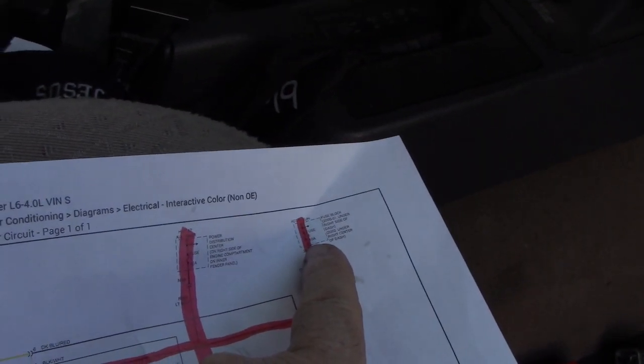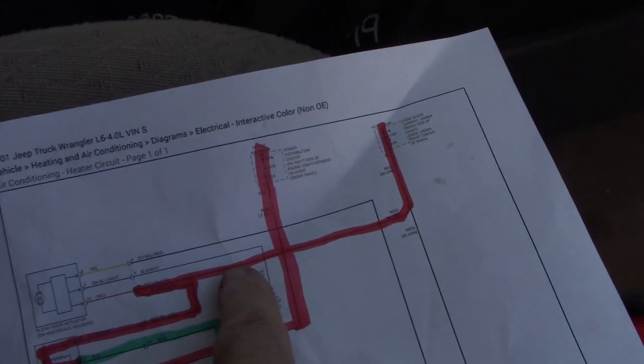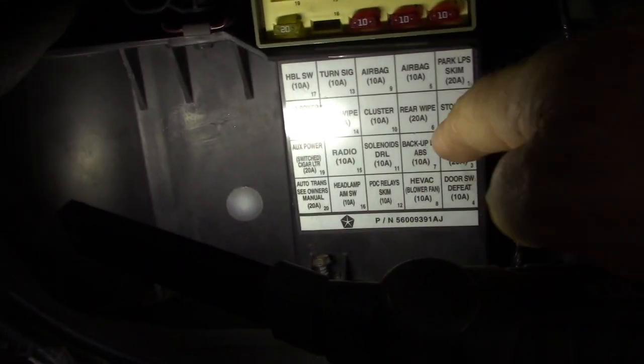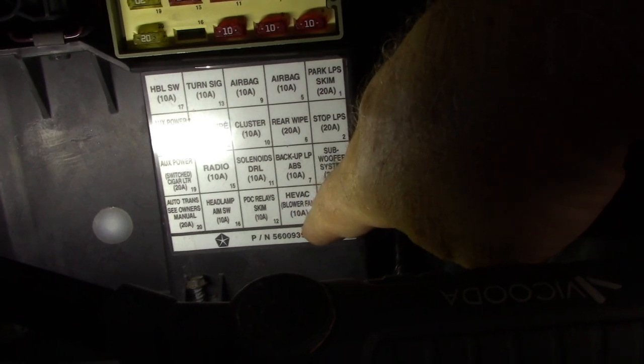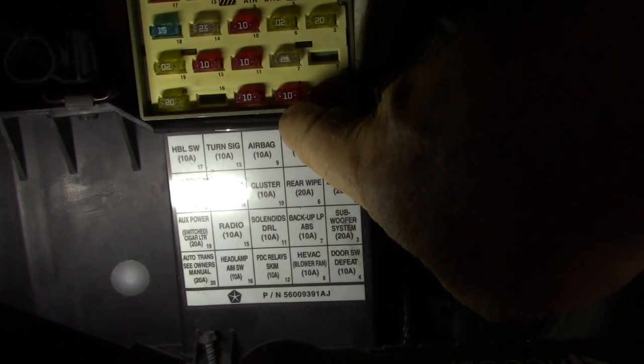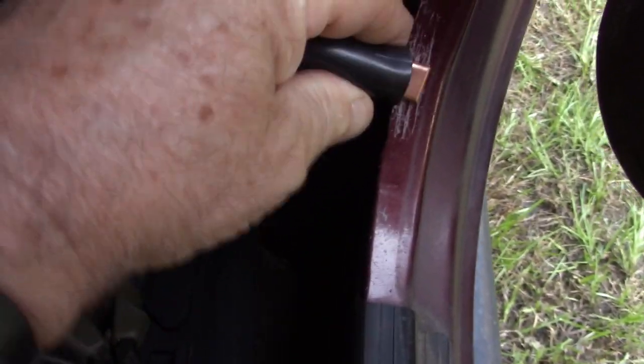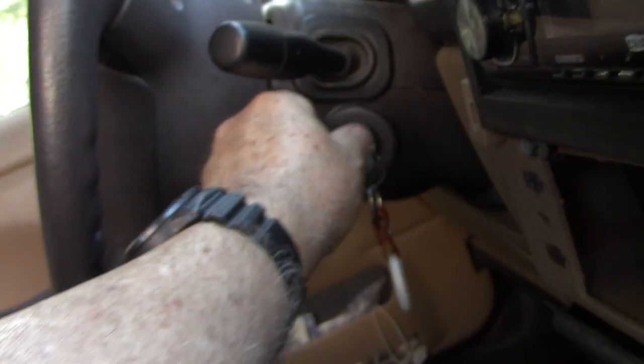Now we got this one, it's switched. Okay, so here's the fuse block, and down here is the HVAC, tells you which one is a 10 amp, and it's right there. Okay, that's the one we want to test. All right, so I'm going to hook my test light to ground here. Make sure I got a good ground. This is switched. Don't forget to turn the switch on. Okay, now it should be energized according to that.